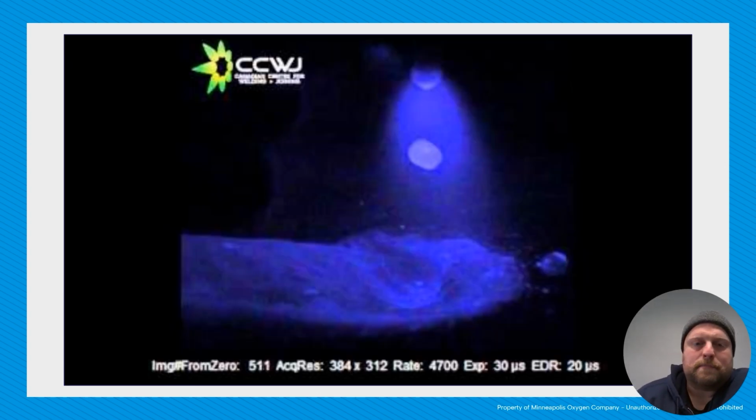All right, and let's look at some pulse welding here. So again, we have a 90-10 mix, it looks like. We're going to be at 250 inches per minute, so that's less than with our spray. And we can see we have arc on, it creates your drop. So arc on, drop, arc off. And you can see that the drops are way more consistent than they were with spray and way more regular. So when we have the arc on, we are melting our stuff. As it turns off, it's allowing that metal in the weld pool to have a little bit of time to firm up before the next drop comes in.